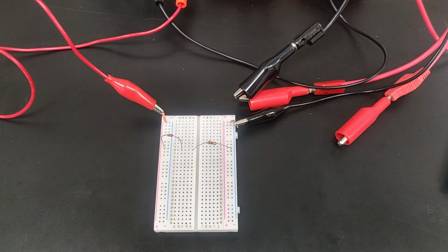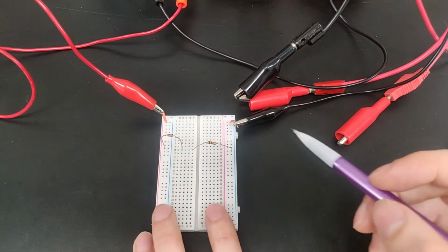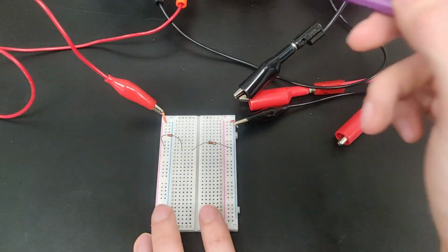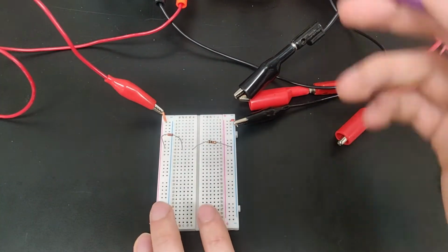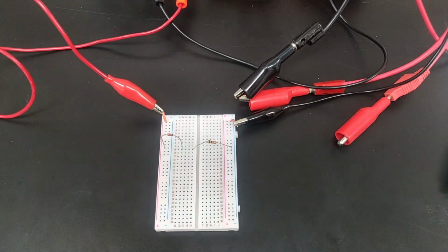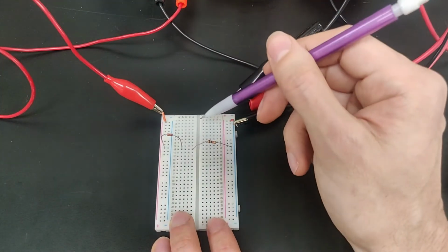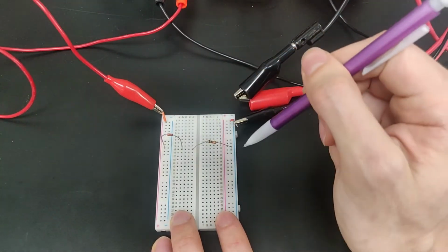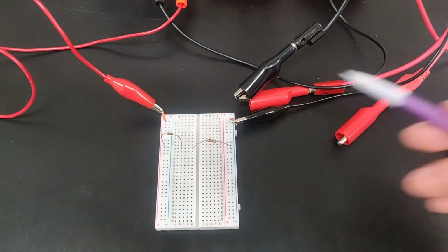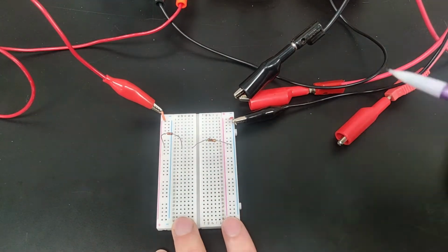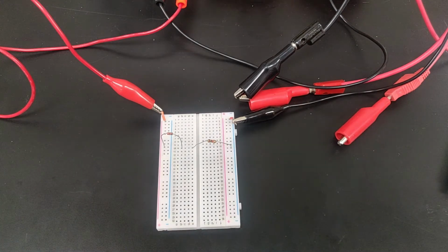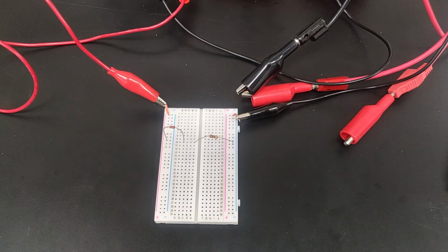So if we want to create this plot of voltage versus current, well, to find the voltage drop, it's fairly simple. We'll attach our alligator clips from our multimeter over it, and we can measure that voltage drop. But to find the current, we can use this resistor. So because these two components are in series and it's just a simple DC circuit, the current going through the resistor is going to be the same current going through the diode. So if we measure the voltage drop over the resistor and then actually measure its resistance, then we can calculate the current using Ohm's law.